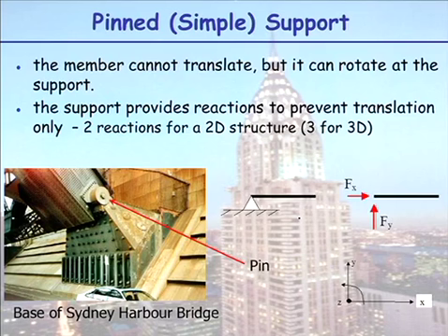So I can't pull down at that point, and I can't pull sideways, but you can see there's rotation allowed now. So that's as compared to the fixed, where when I tried to rotate, I couldn't rotate. So that's a pin connection, and that's a fixed connection. So 3 unknown reactions at a fixed, 2 unknown translational reactions at a pin.